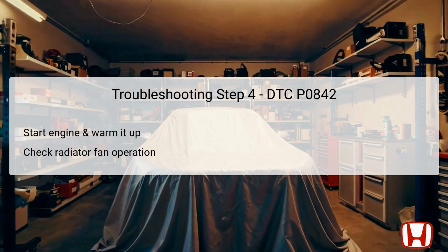During this stage, monitor the vehicle's behavior and be prepared to conduct a test drive to gauge the transmission response, which leads to the next step in your diagnostic process. Drive the vehicle in third gear with the shift lever in the Drive (D) position for a minimum of 2 seconds. This simulates real driving conditions and tests the functionality of the transmission under load.